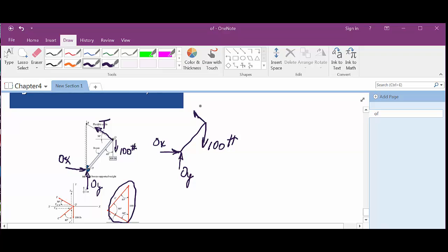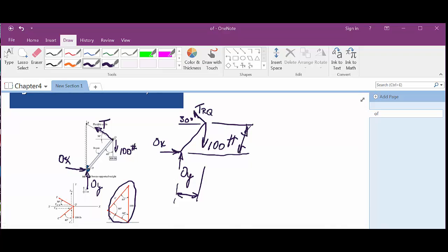Tension in this cable. And what I would say there is the tension in RQ. Is that cable's labeled RQ, right? So I would say the tension in RQ. Then you would have to give the angle right here. And then we also would need this distance. And we would potentially need that distance there. Okay? Eventually what would come into play there would be something about a moment. So we'd have to have the distances. Alright?